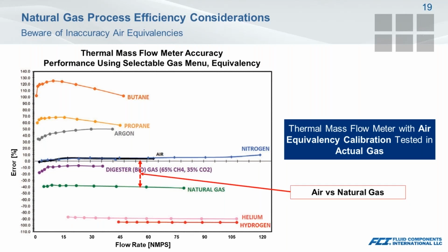And if you look at that, there's a great error just associated with those differences in the properties. And on top of that, if you were to overlay those lines on top of one another, a linear correction is not just going to be a perfect fit here. You've got some discrepancies at the low end. You start getting some nonlinearity between the two curves at the higher and mid range, and all of these lead into inaccuracies in our measurements.